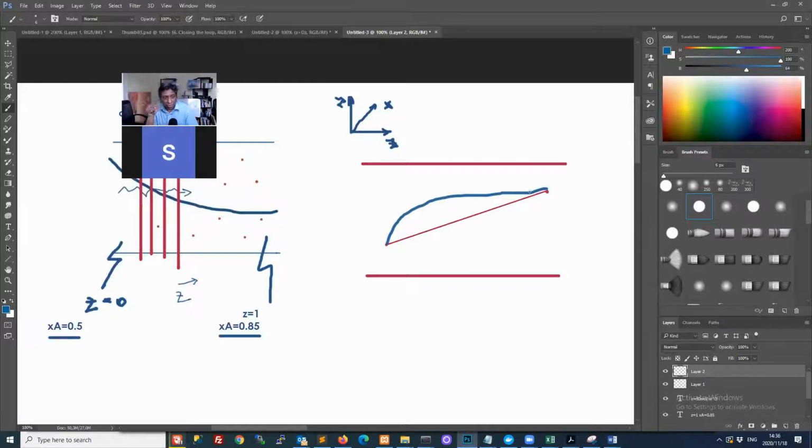It means that there are different concentrations in between. And if, for example, this tube was actually a pore in a catalyst particle, that means we've got different concentrations at each point. That means the reaction rate in the equimolar counter diffusion case will be quite different to the reaction rate in the component A not diffusing case.